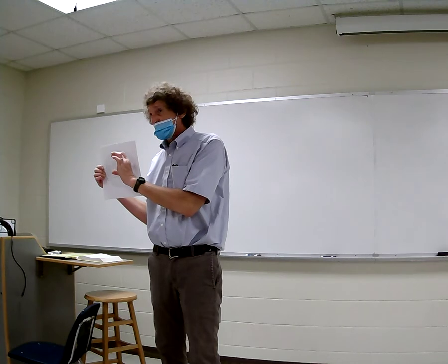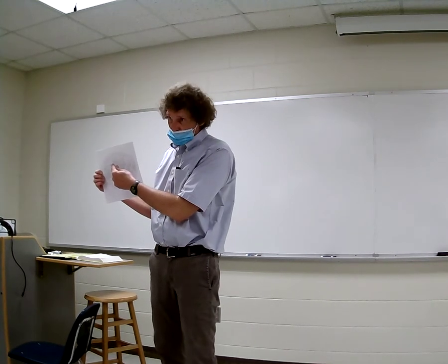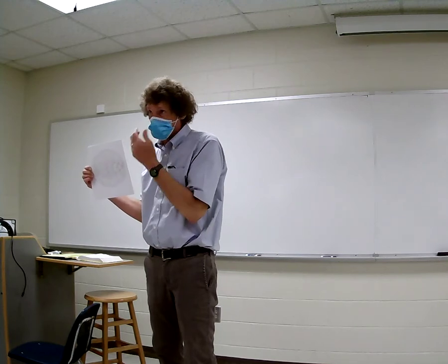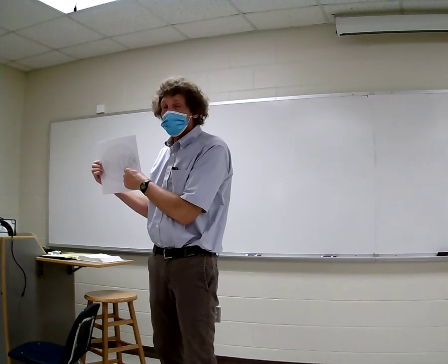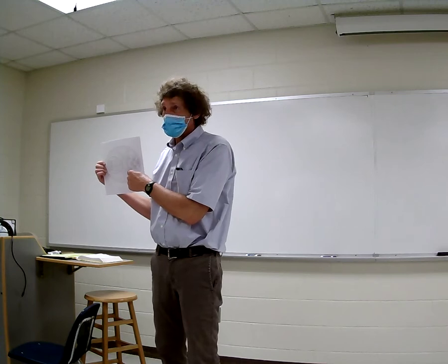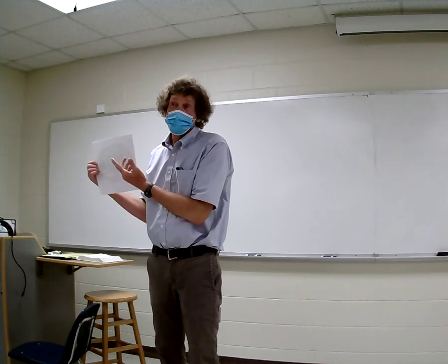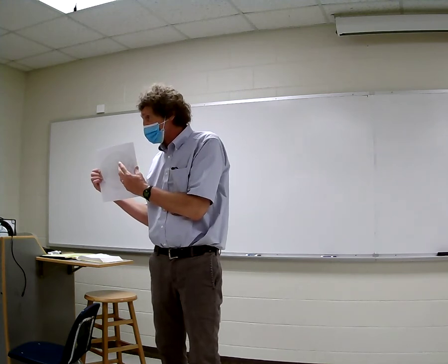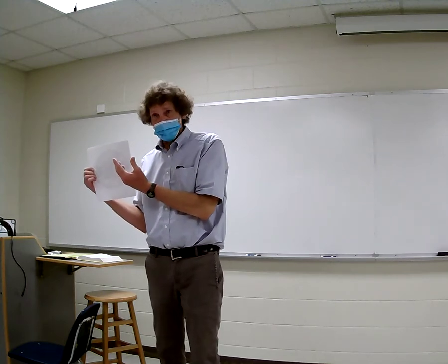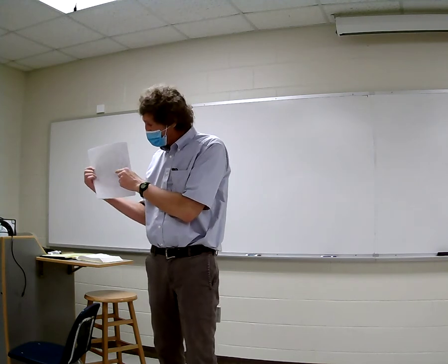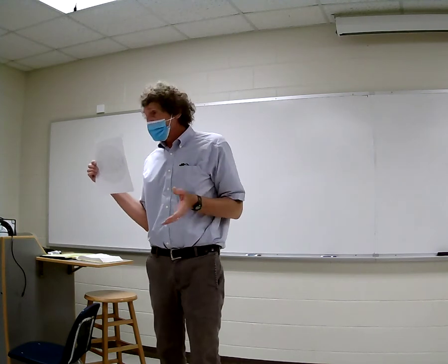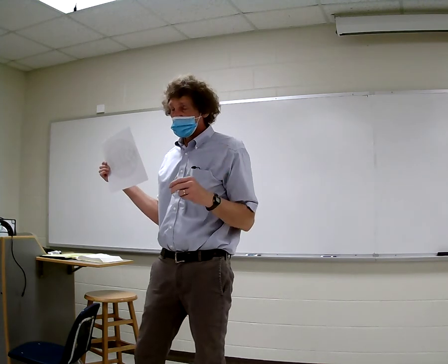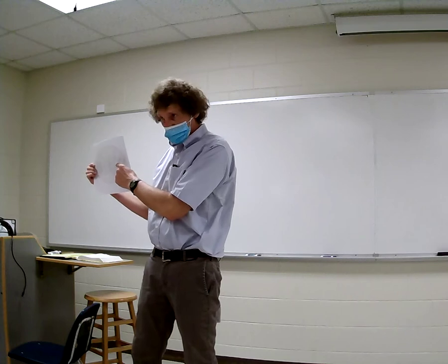Then, after that, you get to the rim of this rotated circle, and you go back to the impedance domain, which is just 1 over the admittance. So now you're over here, and you have to see what to add in series to get rid of the remnant J term, the plus or minus J something. You add the opposite value of that to get rid of it. So you'll have a value of 1, which puts you right at the center, and that means your impedance is matched. Now that's if your normalized impedance lands inside the one circle.